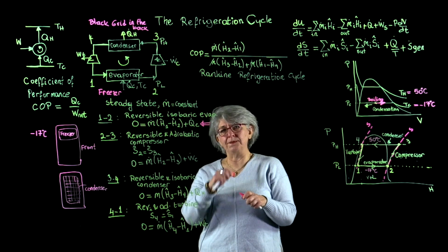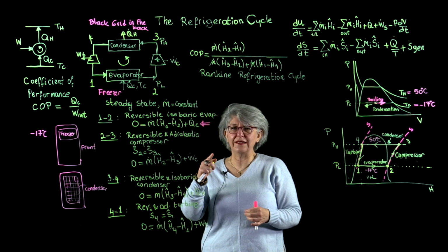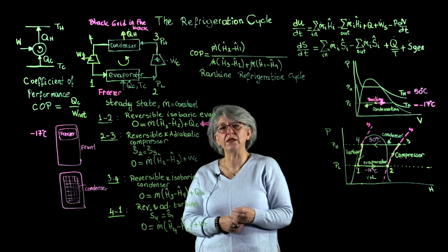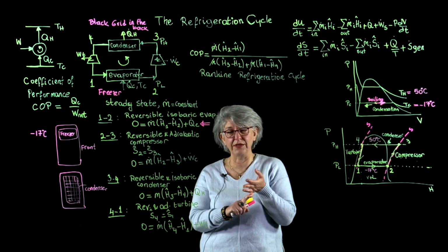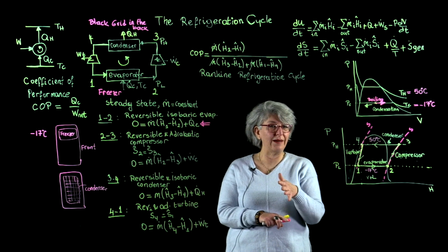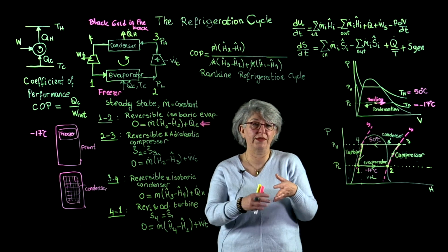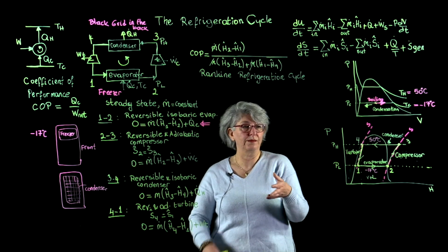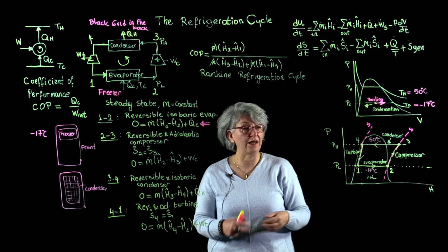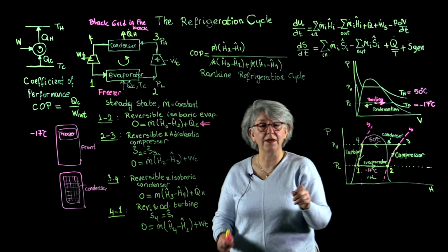Now, excuse me. Now let's just step back and ask ourselves this question now. Which fluid is going to boil at minus 17 degrees Celsius around atmospheric pressures, right? I don't really want to play with vacuum. Either one of those pressures should be atmospheric, and I would rather have this at atmospheric pressures, all right?